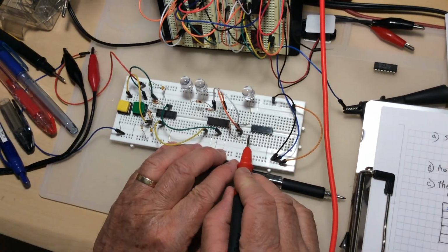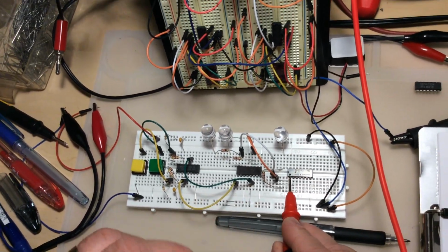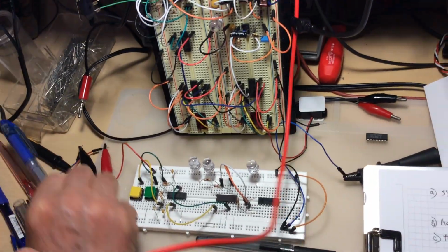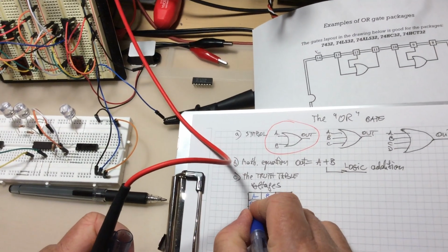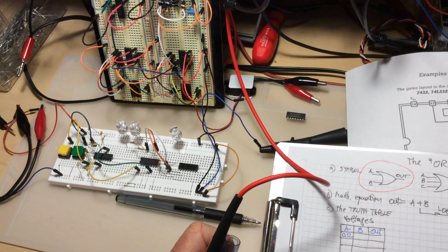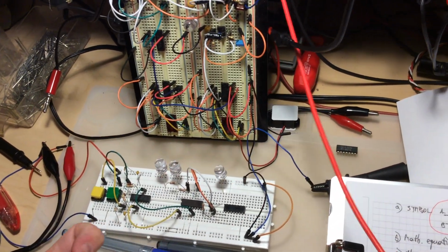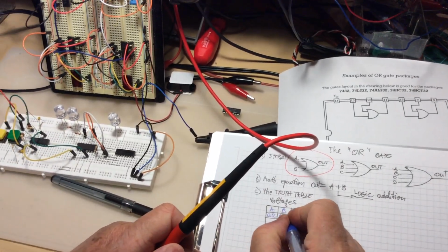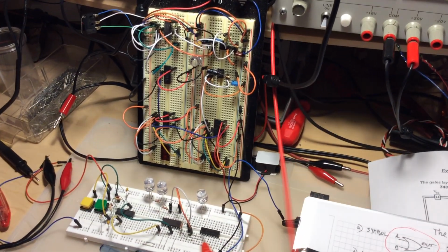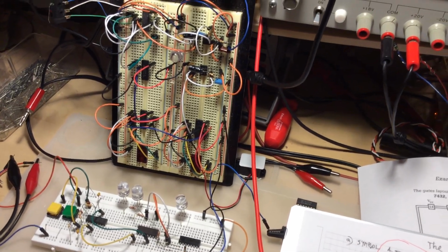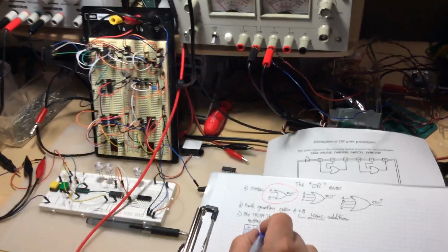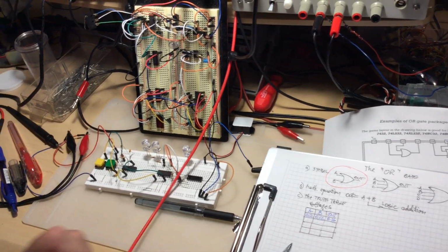So if I measure pin number 1, which is the input A, what do I see on the meter? I see 0.12 volts. It's not exactly 0 volts, but it doesn't matter. I write it here, 0.12. All the values I'm writing here are in volts. I measure now the input B. The input B is on pin 2. It's also 0.12 volts. I write it here. And I measure now the output. The output is pin number 3. What is on pin number 3? 0.16 volt. I don't care about the other decimals; 2 decimals are good enough. 0.16 volt. So far so good?